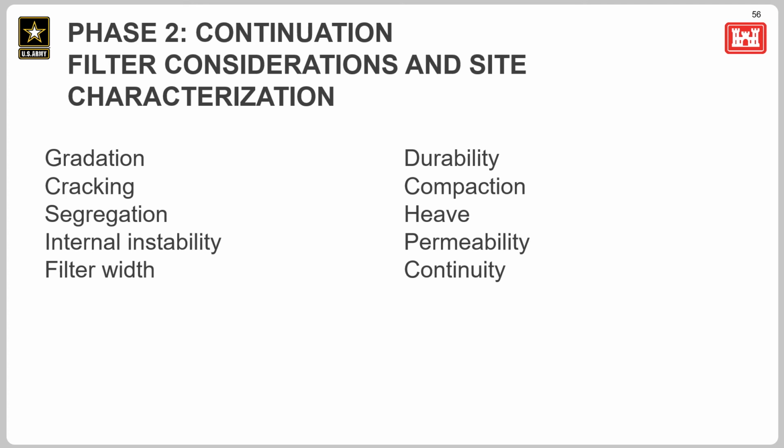Could there be heave due to insufficient cover if the filter is the only material on the downstream embankment face? Is the filter of sufficient permeability? Are downstream zones performing their required drainage functions? What is the continuity to an open face or an extensive void space in coarse soils or bedrock for eroded finer particles to travel to?